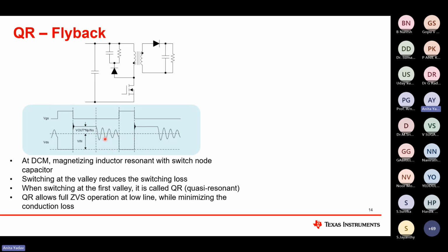Then this ringing from here to here is N·Vout on either side, and thus the plateau voltage for this switch node is Vout × NP/NS + Vin. So when we design our QR flyback, the FET ratings need to be higher than this voltage, and the voltage above this, basically called the overshoot voltage, plus Vout × NPS, determines the capacitor rating of this clamp capacitor.